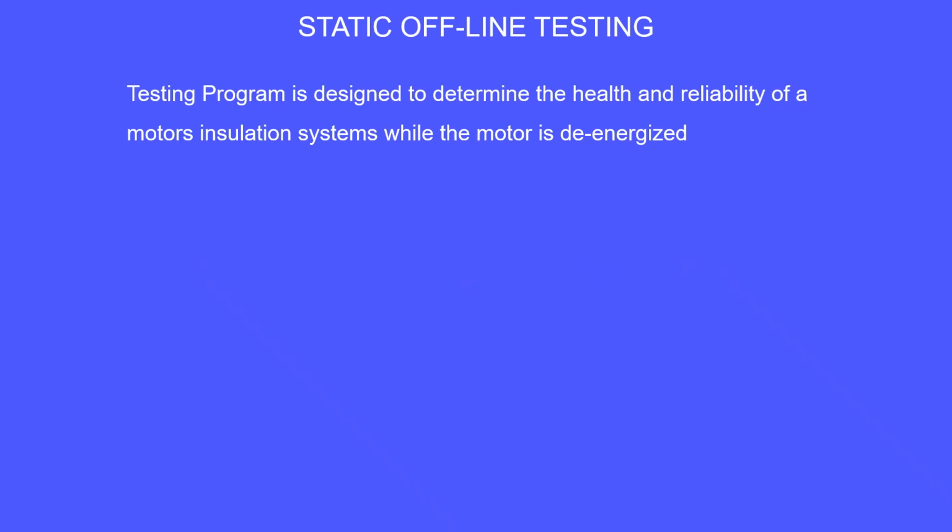A static test program is designed to determine the health and reliability of the motor's insulation system while de-energized. We will be interrogating both the ground wall insulation integrity as well as the turn-to-turn insulation integrity. If your testing program does not interrogate both, you will miss issues.